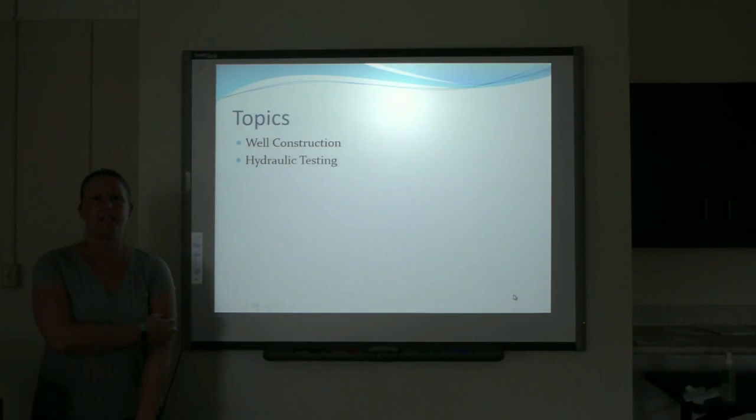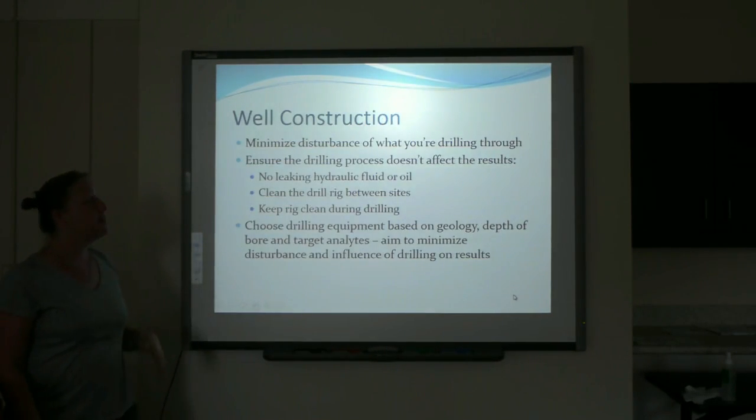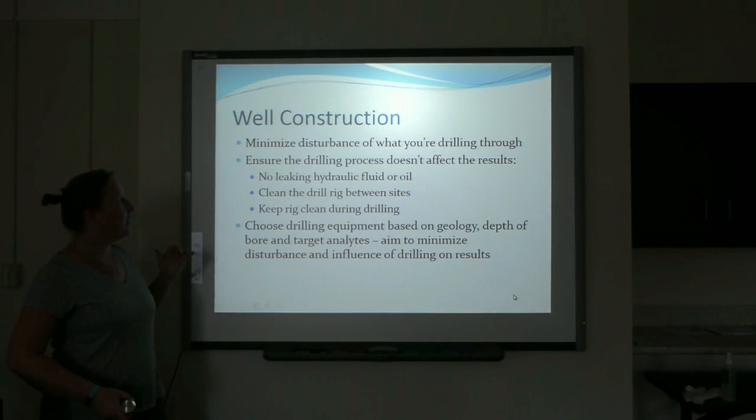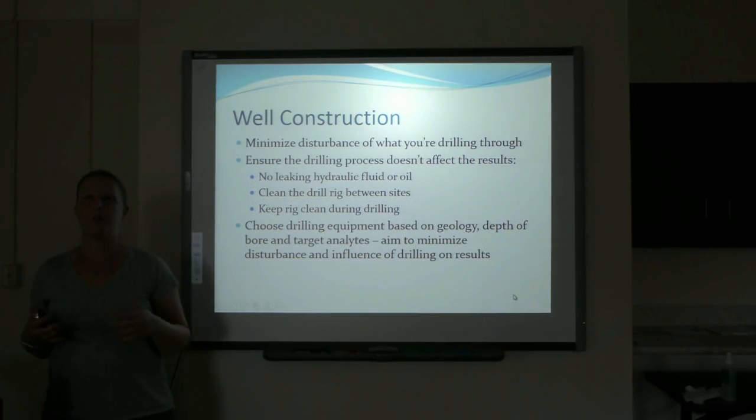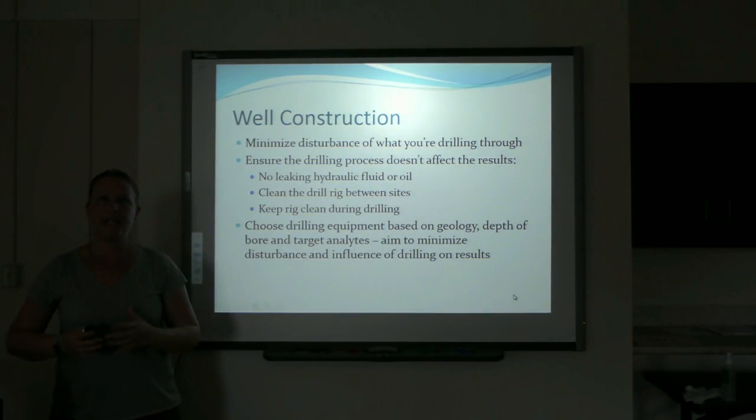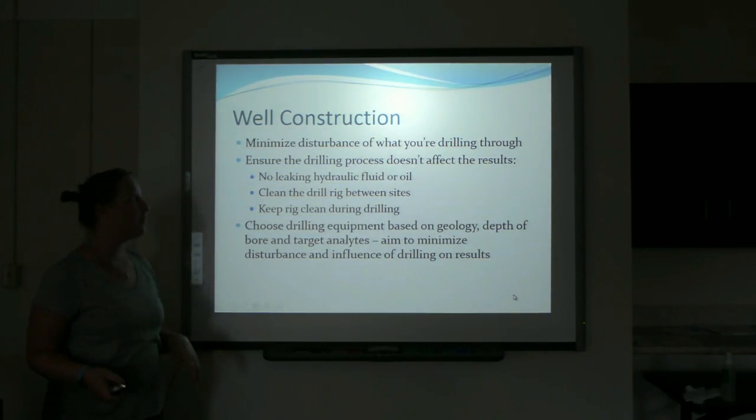In this video we're going to continue talking about groundwater sampling by covering well construction and hydraulic testing. So when we talk about well construction, really what we're focusing on is minimizing the influence of how you drill the wellbore, and the wellbore itself, on your sample, and on having the right type of drilling equipment for your geology, and on screening or allowing interaction between your target formation and your wellbore. And I'll show you diagrams of that in a moment.